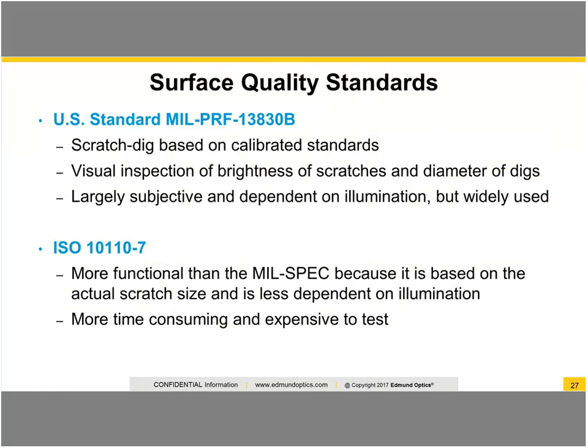There's two standards that we use when we talk about surface quality. The first of those is the mil spec, the PRF 13830B. That's based on calibrated standards and a visual comparison between those standards and the optic that you're testing. That visual inspection, of course, is largely subjective. It's dependent on illumination, the index of the optic, and so forth. But it's widely used because it's relatively inexpensive.